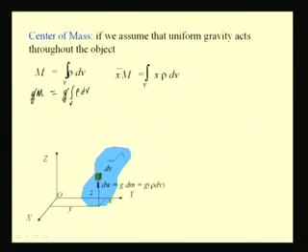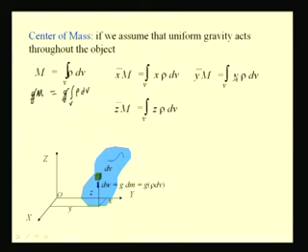So, from this expression we get the coordinate x bar, or the location of this point through which it is assumed that the complete mass m acts with respect to, say, the plane Ozy. In the same way, the other two coordinates, that is y bar and z bar, can be computed by taking the corresponding first moment of this mass. So, this coordinate x bar, y bar, z bar defines the center of mass.